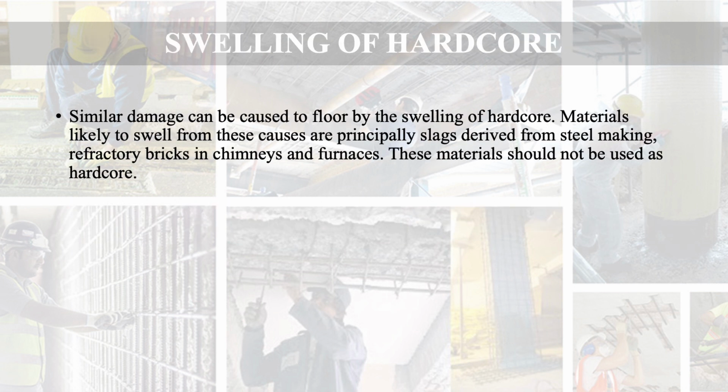Now let's see swelling of hardcore. Similar damage can be caused to floors by the swelling of hardcore. Materials likely to swell from these causes are principally slags derived from steel making, and refractory bricks in chimneys and furnaces. These materials should not be used as hardcore. This should be kept in mind.